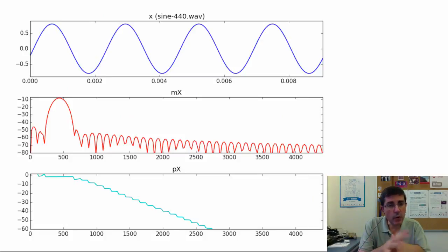So if we start from a sine wave and we want to show the plot of one single spectrum of this windowed sinusoid, we can see it like this. This is the positive spectrum. We don't see the two windows, we only see the positive one. So we are seeing the positive frequencies, and so the contribution of the positive exponential.